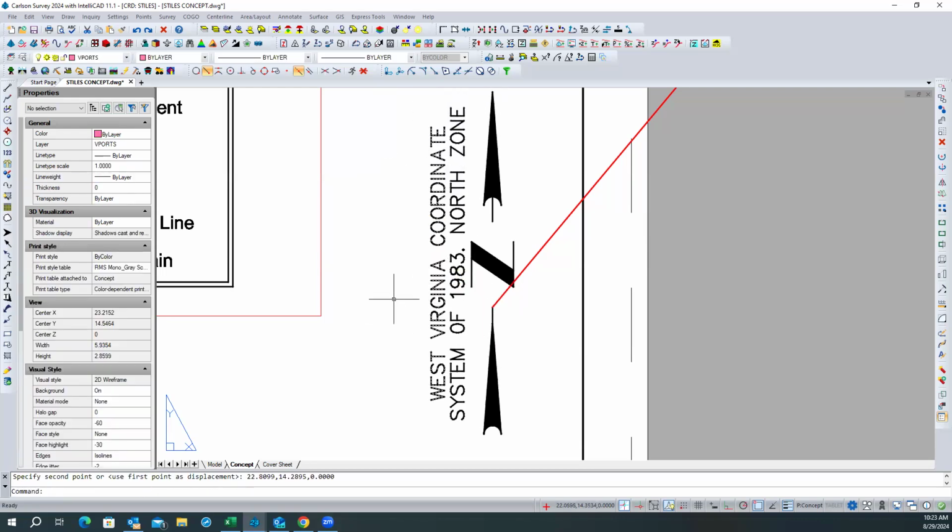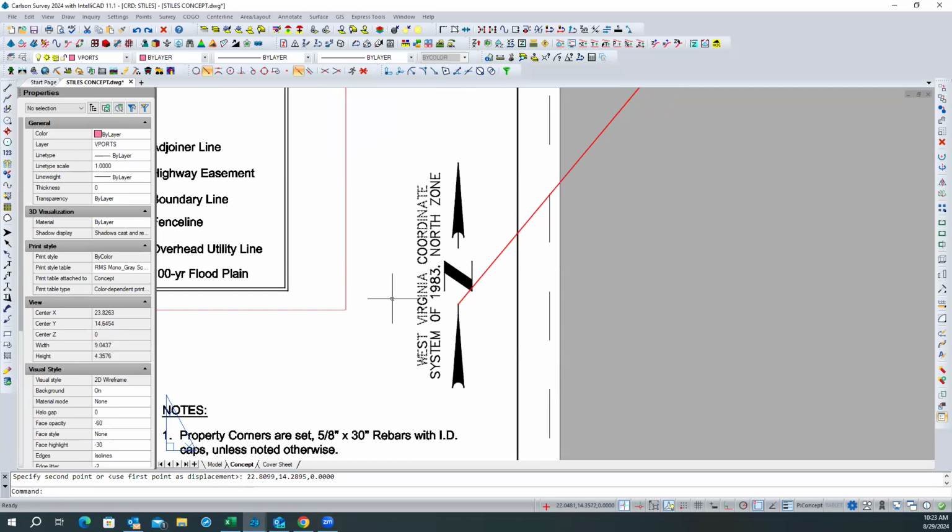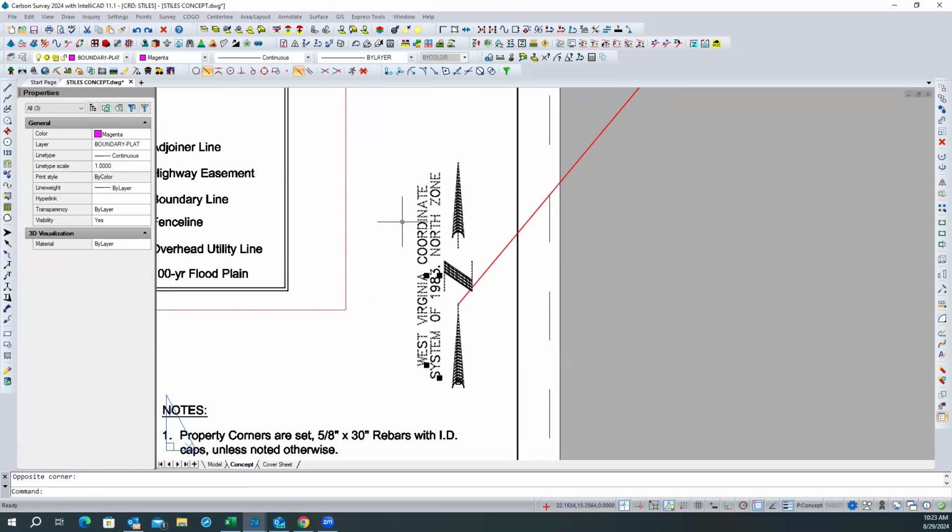So I've got a rotation point that's going to line up. Now, I'm going to take those same three items and I'm going to rotate. And that is my little icon over here. As for a rotation point, here's the rotation point. Now, if I just move the mouse, it's going to go around. But what I want to do is type, you see there, it says specify the angle or use copy or base angle.